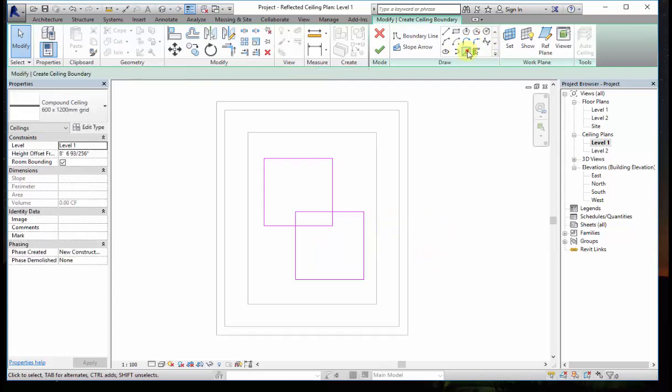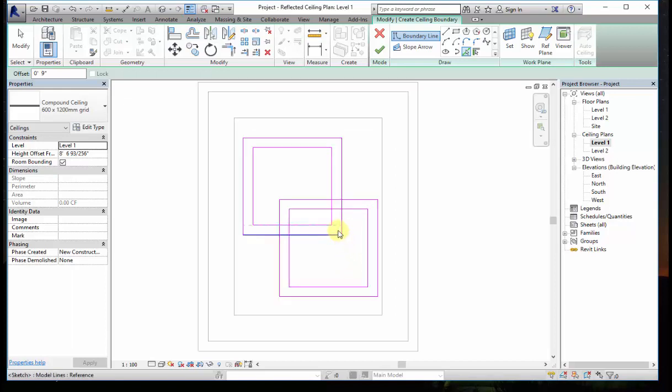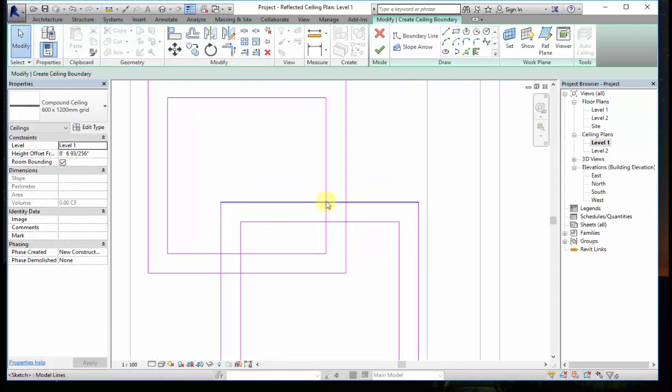Okay, so later here again I'll select pick line and I'll give the thickness of the box, that is this thickness. I will consider the thickness as somewhat around 9 inches. So give the offset for the box like this. Okay, so as per the rule of edit profile, from one point only 2 lines can pass. So these lines are unwanted. So here what I'll do, first I will split it here in between and I will trim the lines. So you are going to remove all the unwanted lines which you don't need.